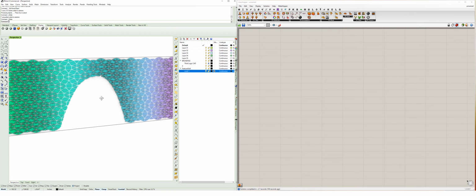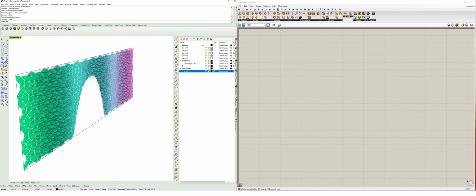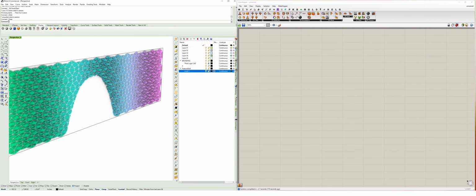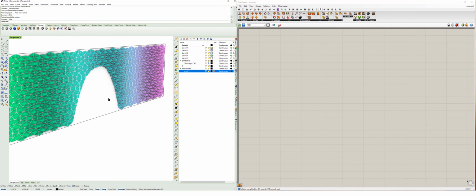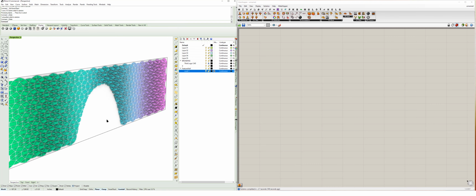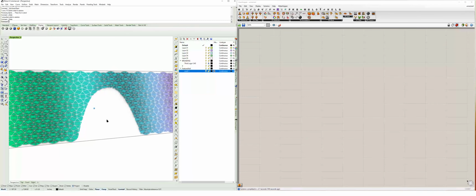I realize that's a destructive method, but be sure what you want to do and how you want to define your opening before you start slicing. You can always regenerate your feature wall in Grasshopper and repeat this process, but that at least gives you a way to make your edits.